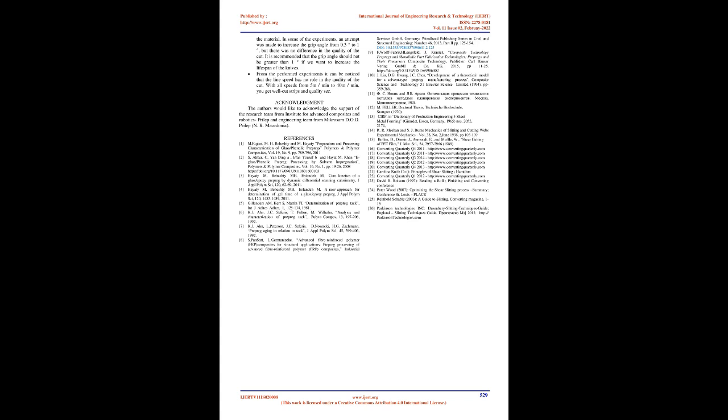The grip angle between the knives is always the same and is about 0.3 degrees regardless of the thickness of the material. In some of the experiments, an attempt was made to increase the grip angle from 0.3 degrees to 1 degree, but there was no difference in the quality of the cut. It is recommended that the grip angle should not be greater than 1 degree if we want to increase the lifespan of the knives. From the performed experiments it can be noticed that the line speed has no role in the quality of the cut. With all speeds from 5 m/min to 40 m/min, you get well-cut strips and quality section.